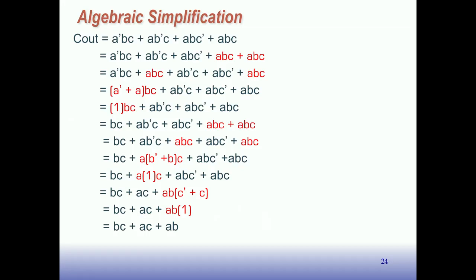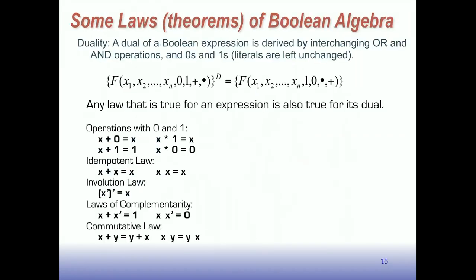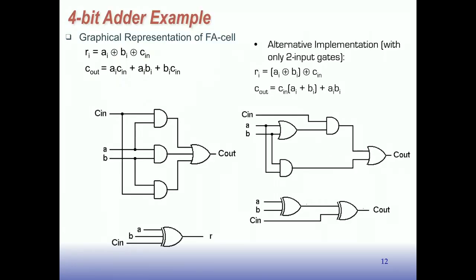Oh, so every circuit we've been talking about so far is 2 levels. You have ors of ands here. I'll give you an example back at when I showed you the adder. It's a good question. So this is 2 levels. You got 1 level ands, 1 level or. This is 3. We have or followed by ands followed by or, right?